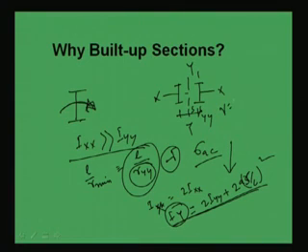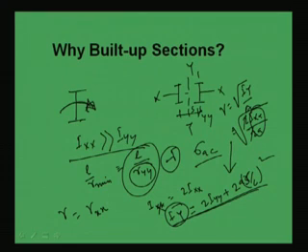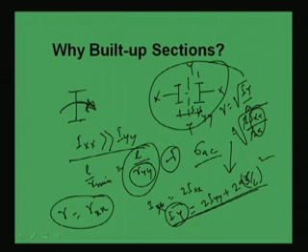Now, what is radius of gyration? Radius of gyration is root of Iy by A, or Ix by A. In the x direction, 2 Ixx by 2A, so finally this is Ixx by A, that means r will finally be rxx. So with this combination, rxx is not going to change, but ryy is going to increase. That means the radius of gyration in terms of ryy is increased, so the strength of the member in terms of compressive stress will become more. The permissible compressive stress in the member will become more if ryy is becoming more.